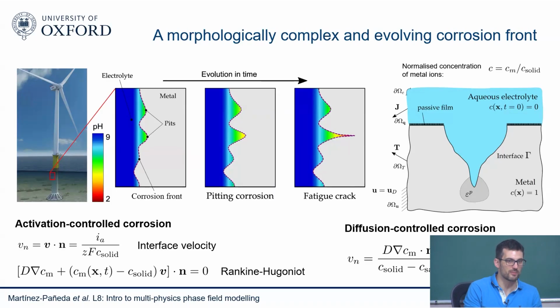When we do experiments, we are forced to do something about it. Some people do experiments in atmospheric corrosion, but it's a bit tricky. In natural corrosion conditions, you are forced to do something. I won't touch on that now, but I have a couple of slides later where I explain that it's not something you can do in commercial packages like COMSOL, but if you have your own finite element code, you can enforce charge conservation, and then you can let cathodic and anodic reactions balance each other, and you can predict natural corrosion. And of course you can change conditions depending on your metal corrosion system, and ionic species as well.